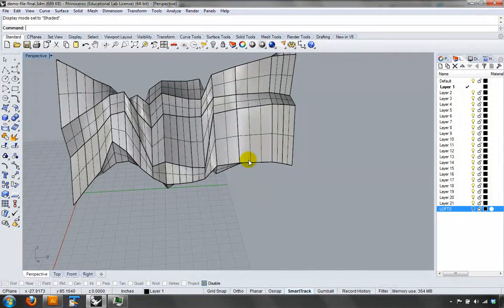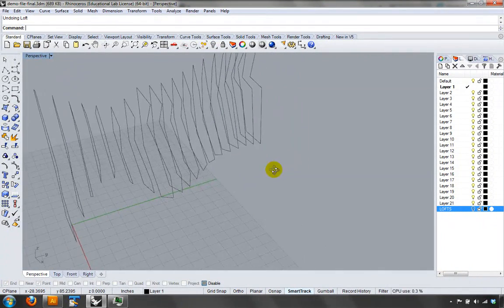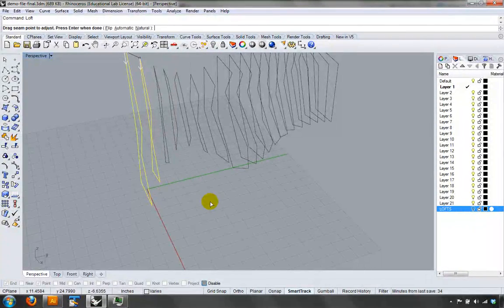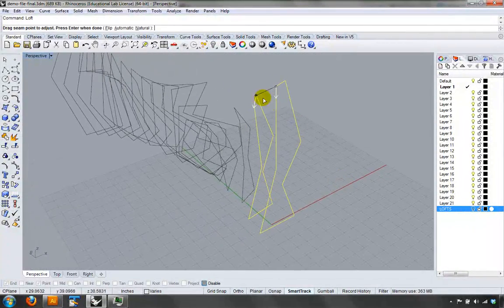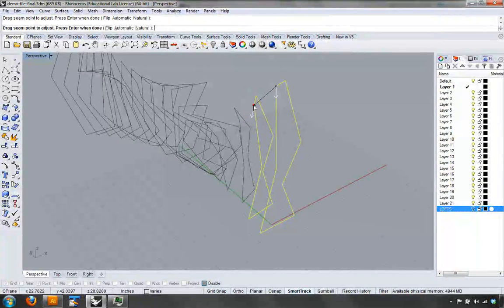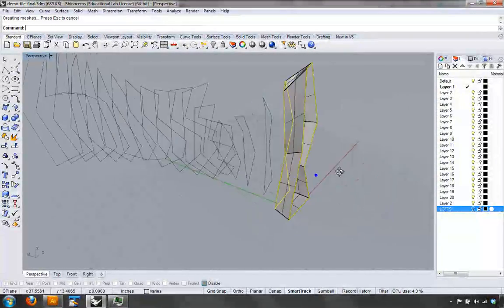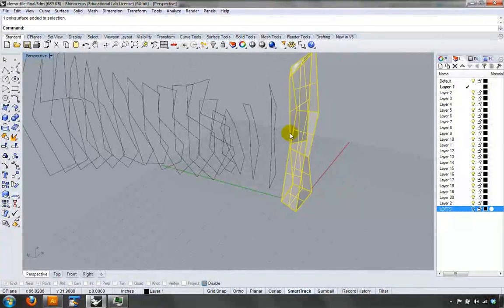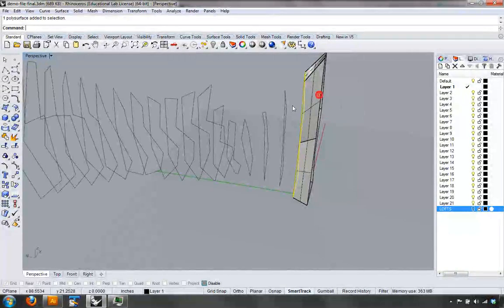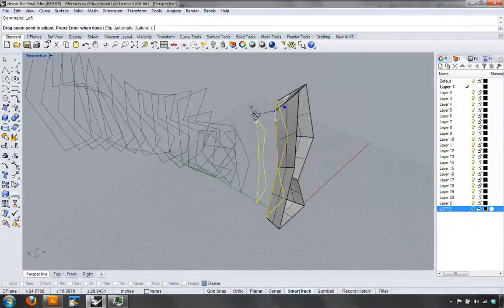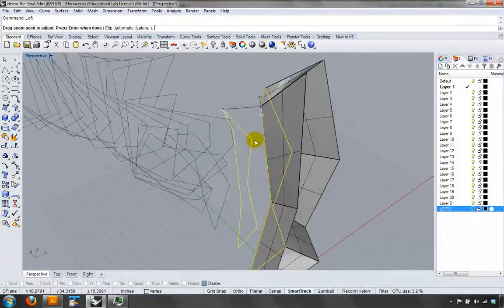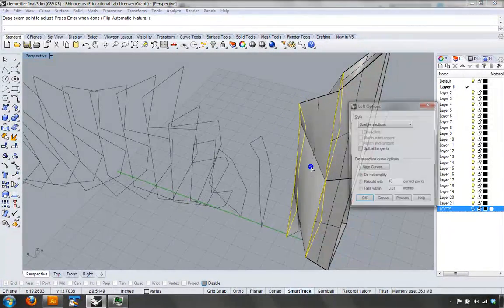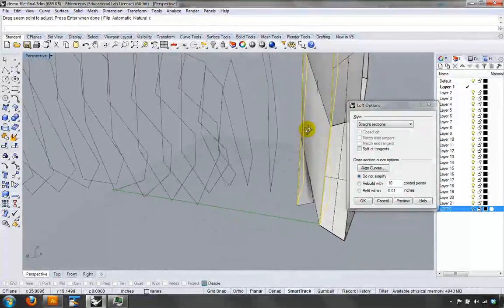A last option that is kind of the nuclear option, because it can be time consuming, but it'll definitely work, is to loft two curves at a time. So I can go to loft and adjust these directions so that I am ensured that I get a straight, clean piece. If I click on the edge here, click on this curve, click on that curve, loft these together. Now, you have to maintain that same order, though, or you can really mess things up. You want to make sure to follow the same point, but at least this way you get a clearer picture of what the thing's trying to do.